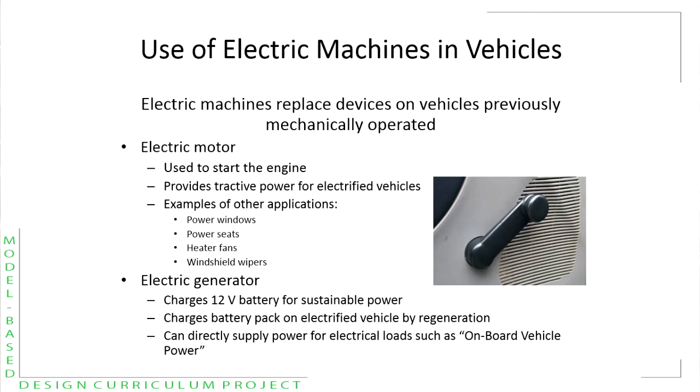There are many other applications that are under the hood of your car. For example, many modern cars use electric water pumps rather than mechanical pumps, formerly driven by a belt connected to the engine. The use of an electric motor is a more efficient solution, especially as the speed of the pump impeller can be changed as the coolant temperature varies.